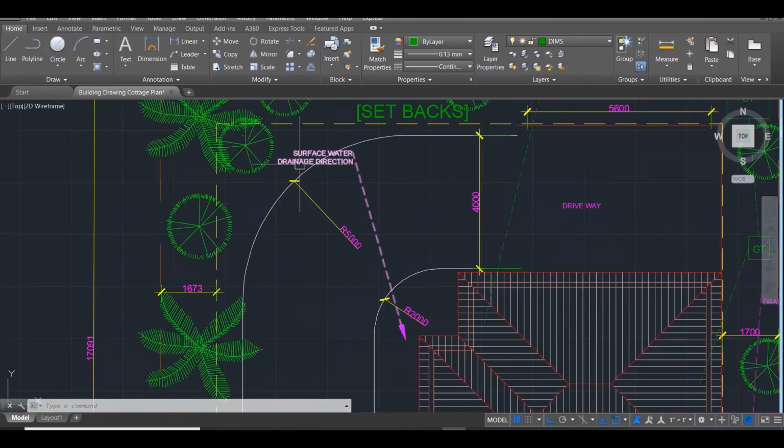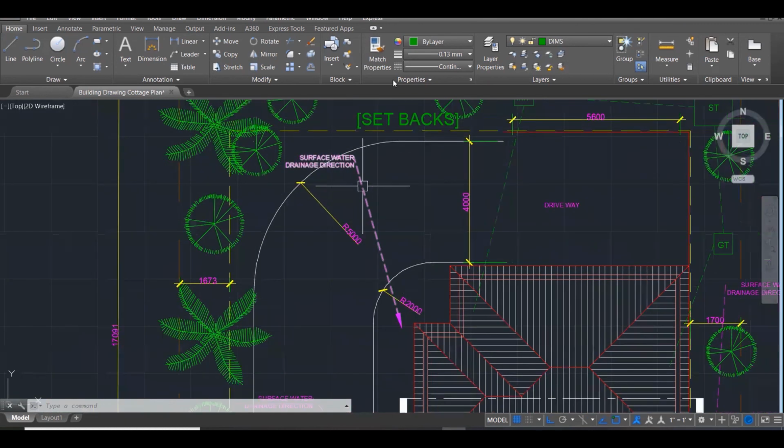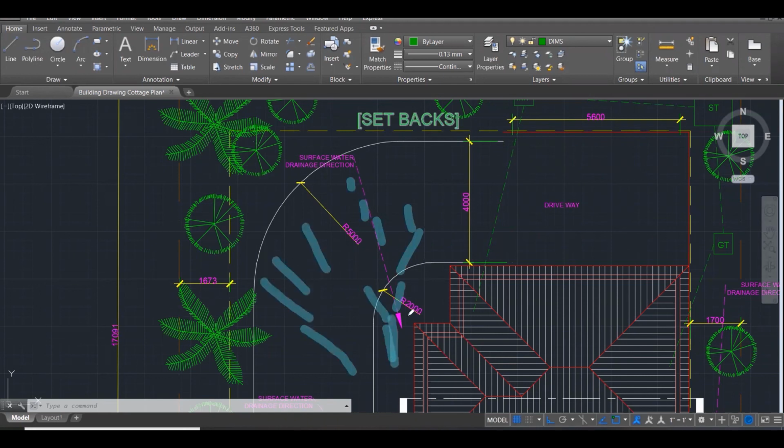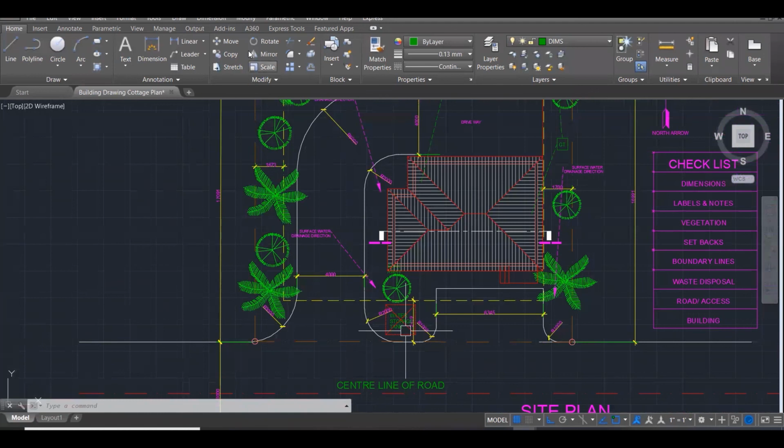Now, the surface water drain in each direction. What is this? This tells me where the rainwater is going to go, how the land is sloping. So the first thing when I'm looking at this, I can see that my rainwater would be coming in this direction here and going down that slope right there, right? It would drain in this area. That's good. That means if I want to catch that rainwater, I know where to set up a catchment point, and I do have a catchment point. I have a water storage tank under here. I can collect rainwater and store it there because the water is being drained to that area. And when I store that rainwater, I can use that to water the plants or even to clean up around the house, clean up on the outside. I can actually reuse the water that I've stored in that area.